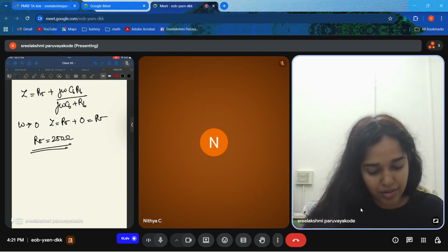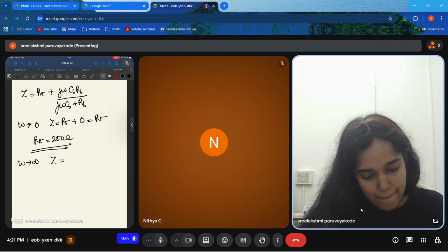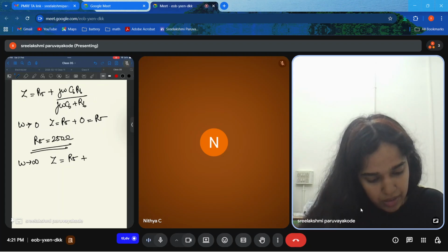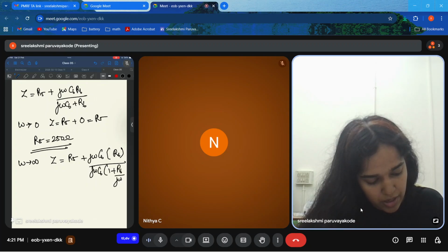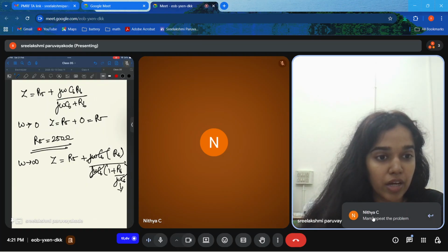Now, how to find R6? Same thing. For omega tends to infinity, what is going to be Z? R5 plus, as I did before, we'll take out j omega C6. We'll have R6 by 1 plus R6 by j omega C6. So this term tends to... okay, what should I repeat? Could you please tell?